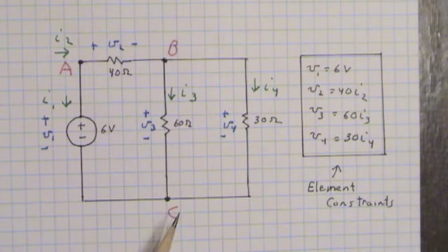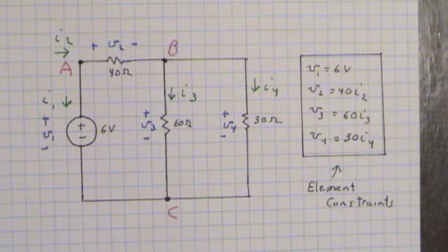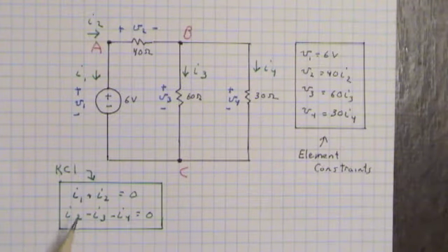We could also write down an equation at node C. It would be a good exercise to do so. You'll find that it results in an equation that is derivable from the equations at A and B. So it's not an independent equation. And here are the 2 KCL equations written in box form. We have 4 plus 2 equations, 6 independent equations. We have 8 unknowns. Where do the other 2 equations come from? They will come from Kirchhoff's voltage law, and that's the next thing we wish to discuss.